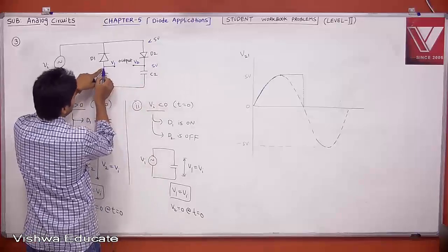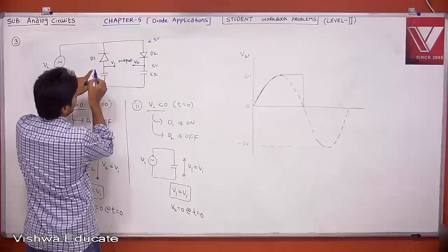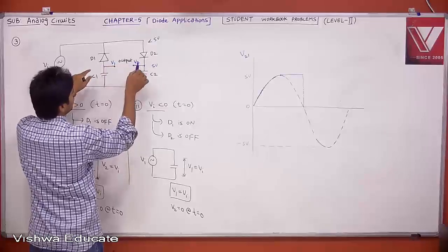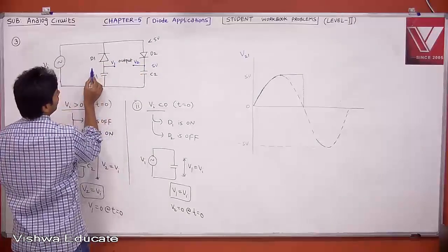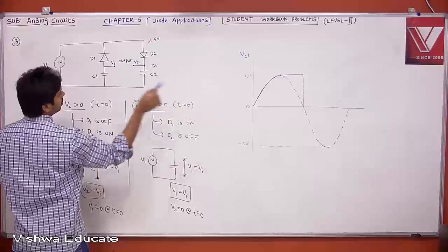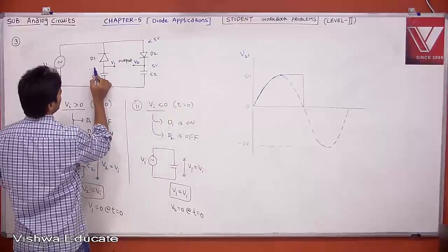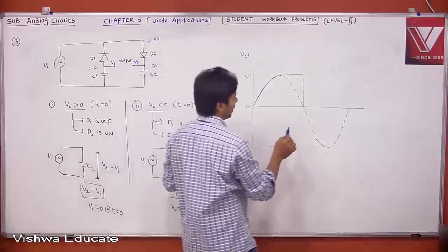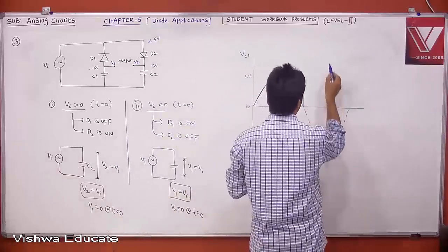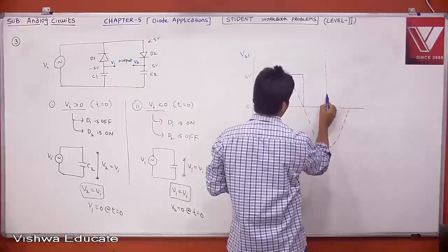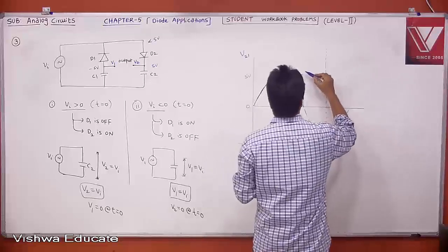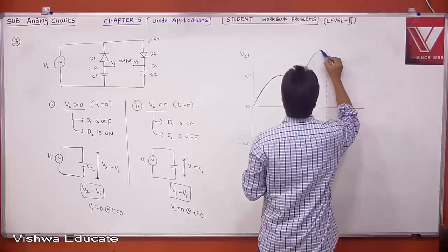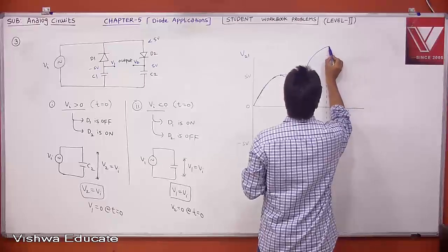Then when this is tracking 0, minus 1, minus 2, minus 3, minus 4, then 5 minus minus 1, 5 minus minus 2, 5 minus minus 3, this voltage is also increasing. Therefore maximum it will go to what? It will go to minus 5 volt. And this is going to minus 5 volt. Then 5 minus of minus 5, it will be 10. Therefore how is it going? In the same way, you can say the sine wave, how the sine wave is going like this, it will also go and it will stay there.